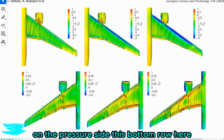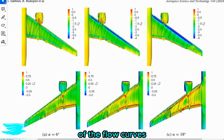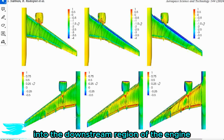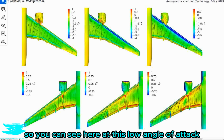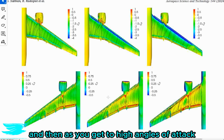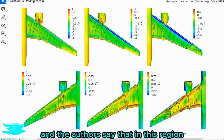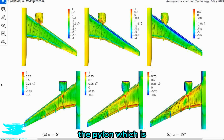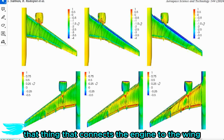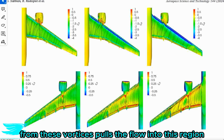Alternatively, on the pressure side, so this bottom row here, as the angle of attack increases, more and more of the flow curves into the downstream region of the engine. You can see here at this low angle of attack, the flow is quite straight as it goes along, and then as we get to high angle of attack, it starts to get sucked in behind the engine. And the authors say that in this region, the pylon, which is that thing that connects the engine to the wing, creates vortices, and perhaps the low pressure in this region from these vortices pulls the flow into this region.